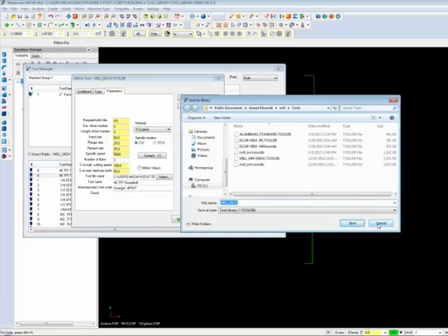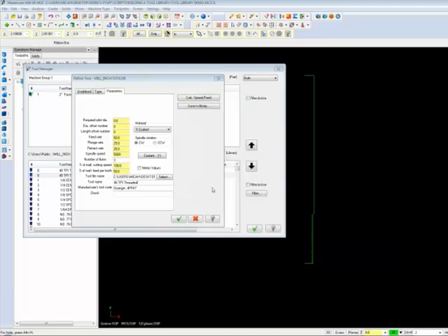Right. Excellent, guys. That's always why I like to have both of you here, because between the four of us, we can usually figure out the answer. One other option is you could just create a Mastercam file. You could create as many tools as you wanted on different levels, and you could just do a file merge at any point in time. That's what I end up doing.